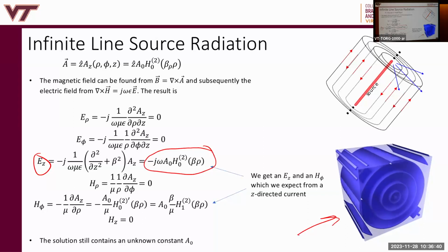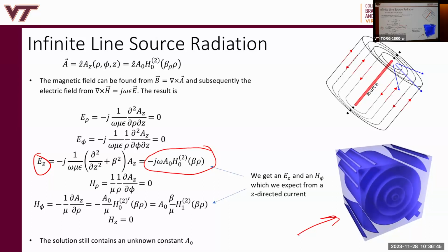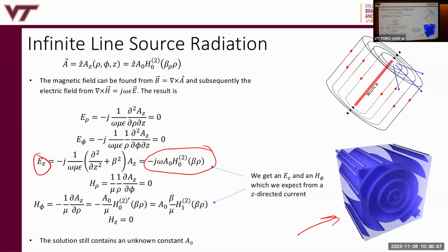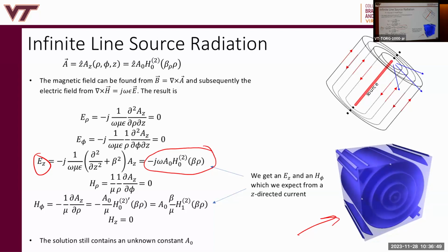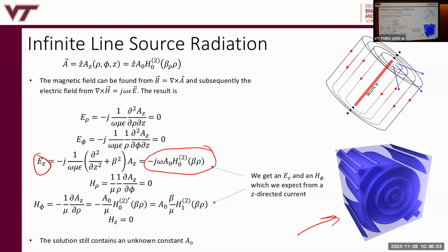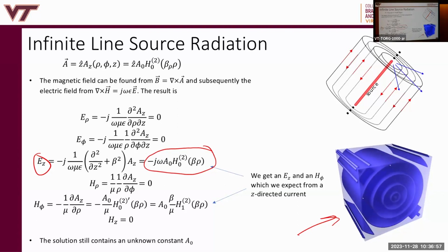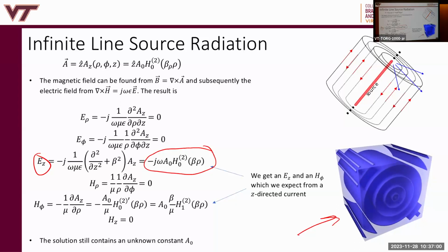With no azimuthal variation. Remember, azimuthal variation is linked to the radial variation. So if we have any azimuthal variation, then it cannot be H0, right? And if we have H0, that's the only mode that has no azimuthal variation, because then M is equal to 0 and azimuthal variation goes to 0, right?